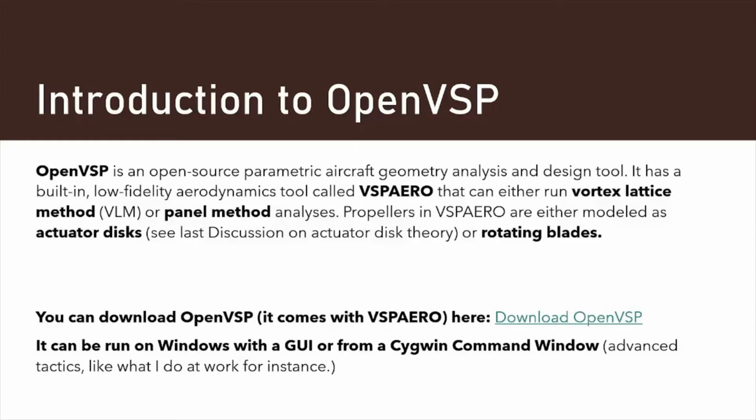It's a good way to quickly model geometries, and also has some analysis capabilities, with a built-in low fidelity aerodynamics tool called VSPAERO that can either run Vortex lattice method, which is VLM, or panel method analyses. I will definitely go over what these are. Propellers in VSPAERO are either modeled as actuator disks, as I mentioned in my last discussion about actuator disk theory, and the code that comes with it, or rotating blades. Though in this case, I believe you will not have to model them in OpenVSP because the code that Professor Chateau gave you should be sufficient to assess the engines that you're using for this aircraft.